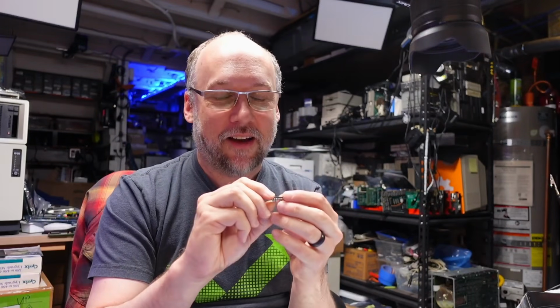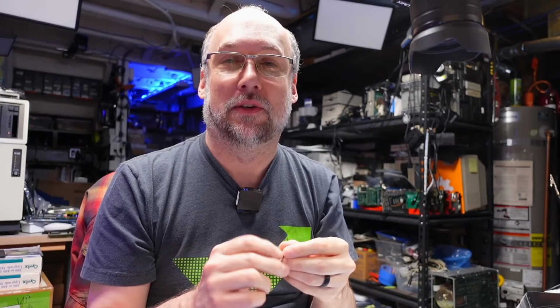It was this bad chip all the time, and I have to say, I've never seen that particular failure before, where it wasn't stuck at 0 or 5 volts, the output. It was leaking the clock signal, but kind of working, because we saw sometimes it would be low when the DRAM input was low, but when it was high, instead of just staying high, it was getting that clock signal on there, and that was causing those particular symptoms that we saw.